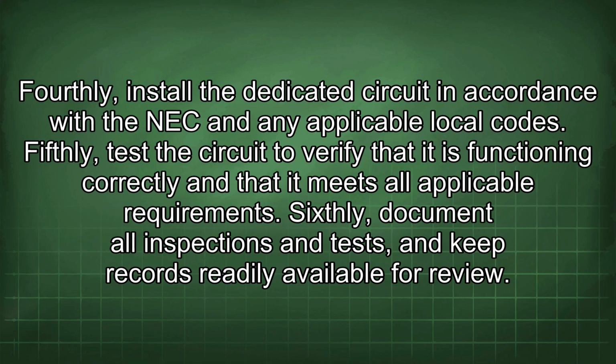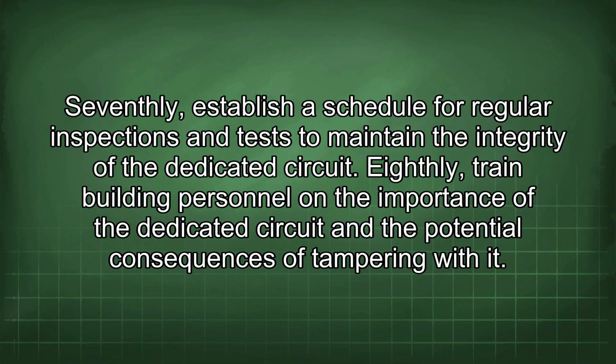Fourthly, install the dedicated circuit in accordance with the NEC and any applicable local codes. Fifthly, test the circuit to verify that it is functioning correctly and that it meets all applicable requirements. Sixthly, document all inspections and tests, and keep records readily available for review. Seventhly, establish a schedule for regular inspections and tests to maintain the integrity of the dedicated circuit.